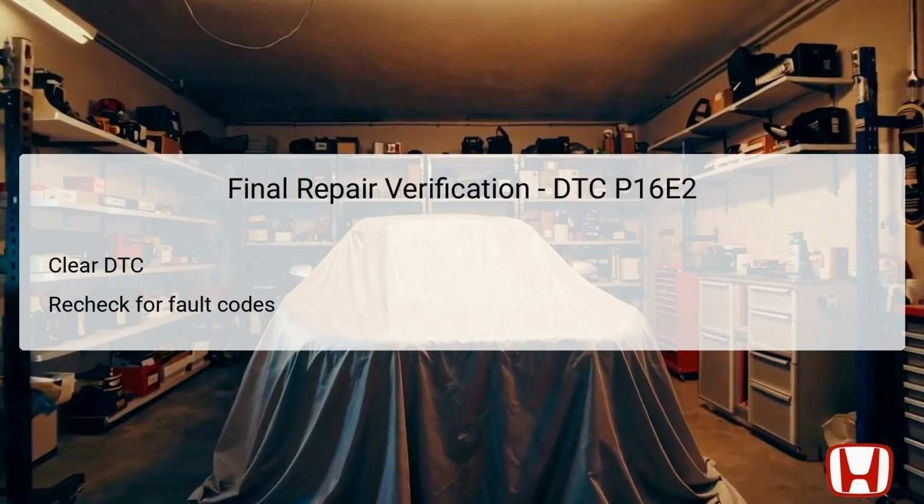If DTC P16E2 or any other related codes are still present, further inspection may be necessary. This step confirms that all systems are functioning correctly and that communication among the alternator, PCM, and LIN network is re-established. Successful verification indicates that the troubleshooting and repair efforts were effective.